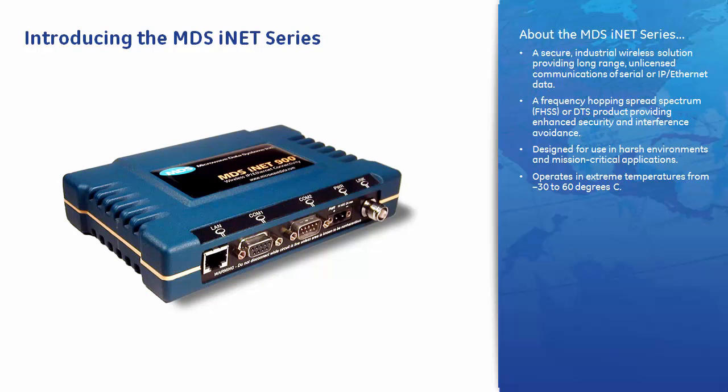So let's review just what the iNET series offers. It provides a secure, industrial-hardened solution for wireless connectivity over long-range signal paths, and it does so under unlicensed spectrum rules available in the US, Canada, and many other countries. The primary band of operation is the 902 to 928 MHz spectrum. Special frequency bands such as 300 MHz, used principally in China, also exist, but the focus of this module is on 900 MHz, and this is denoted by the model number of MDS iNET-900.